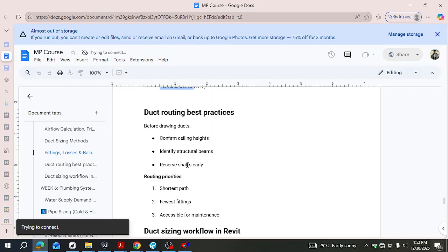But there are some cases where you may need to go through a floor. Try and avoid it. If I'm designing for multi-floor buildings, especially a commercial building, because commercial buildings usually require ducted systems more because the demand is way higher, right? So I usually like to do one mechanical room per floor. That's the ideal, a mechanical room per floor. And then in that mechanical room, you place your equipment there, and then it goes up into the ceiling and then distributes its air, right?